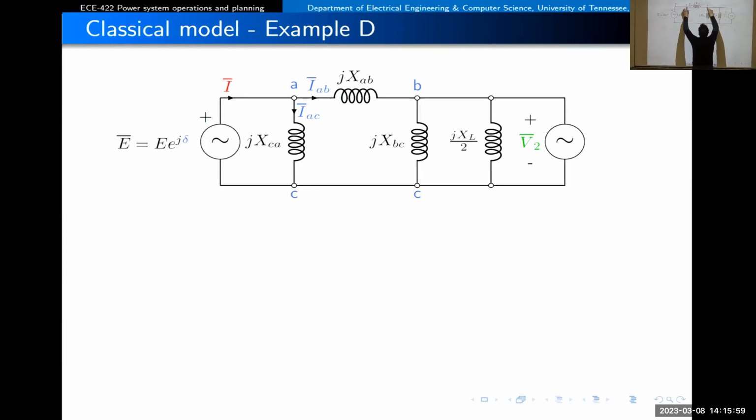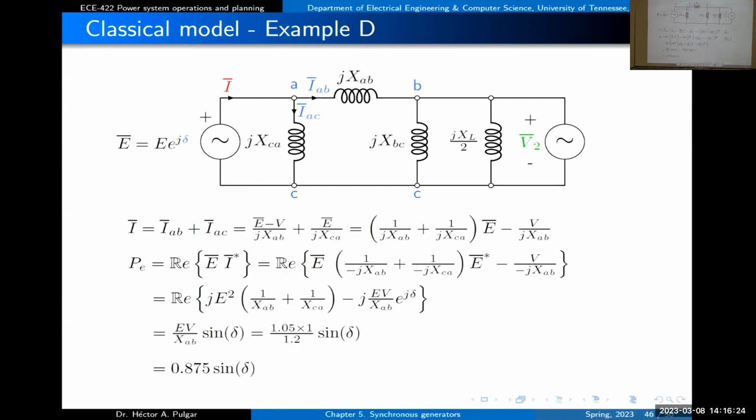With those two voltages, you get the difference divided by the impedance, and then you get the current through that impedance. For this one, also it's easy because the voltage here is the voltage from your generator. You divide that voltage by this impedance, then you get that current. So this star-delta conversion is useful. We can calculate this current easily.